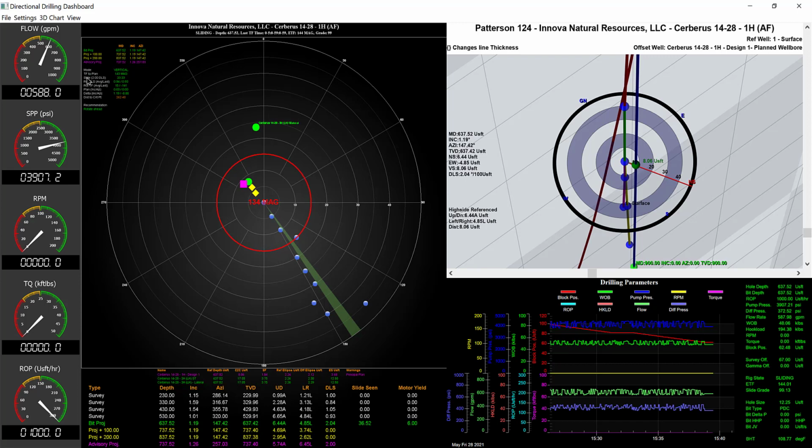We've then got our mode setting, tool face to plan, what our slide is, rotary dogleg severity, rotary tool face, our planned inc and azi, our delta inc and azi from the plan value based upon our current bit projection, and distance to the next critical point on the principal plan, and the recommendation of what we do now in our current state.